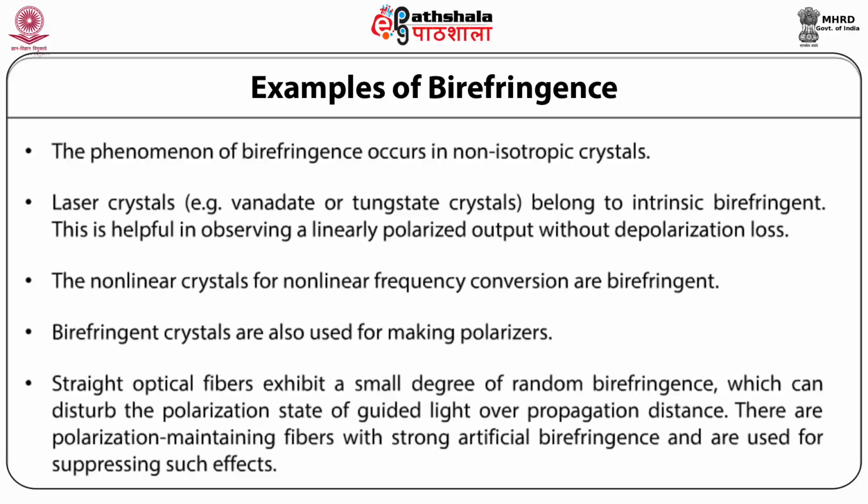Straight optical fibers exhibit a small degree of random birefringence, which can disturb the polarization state of guided light over propagation distance. There are polarization maintaining fibers with strong artificial birefringence, which are used for suppressing such effects.